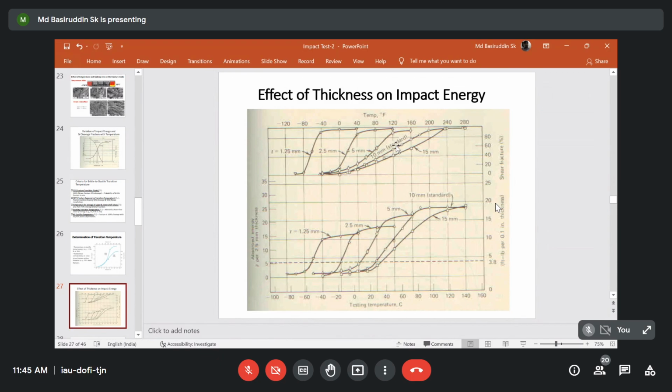So following this particular curve, you can clearly understand how triaxiality is important for measuring the ductile to brittle transition temperatures or the impact transition temperatures, like 27 joule ITT, 54 joule ITT, or 60 joule ITT, something like that.